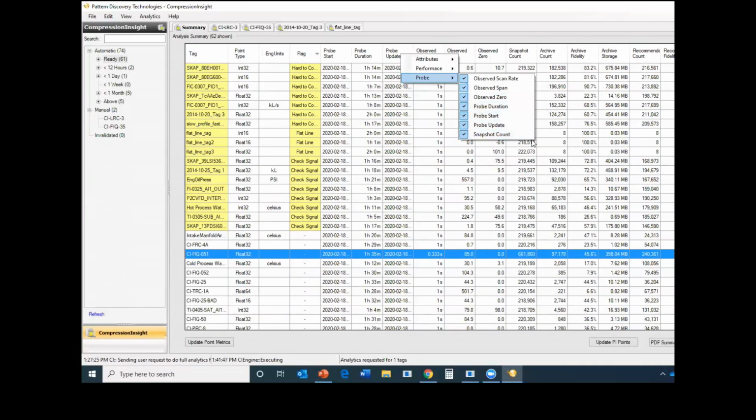We may have a temperature sensor that goes from ambient temperature to 1500 plus degrees, but the normal operation of it is from like 1300 to 1550, right? Yes. That's normal operation. That's where I really need to do my tuning. So for those kinds of people, they really want to tune this tag around where it normally operates.